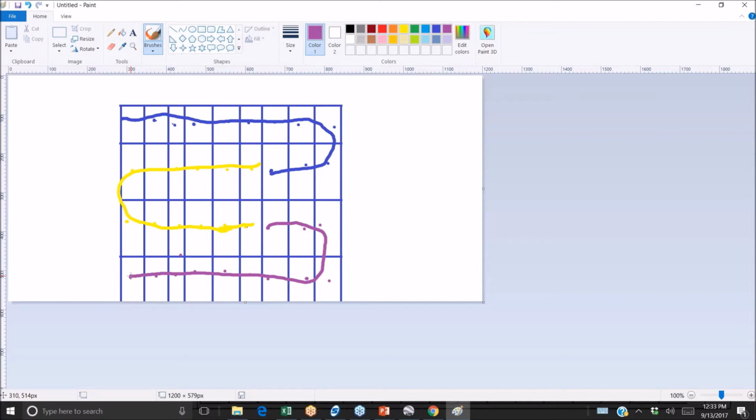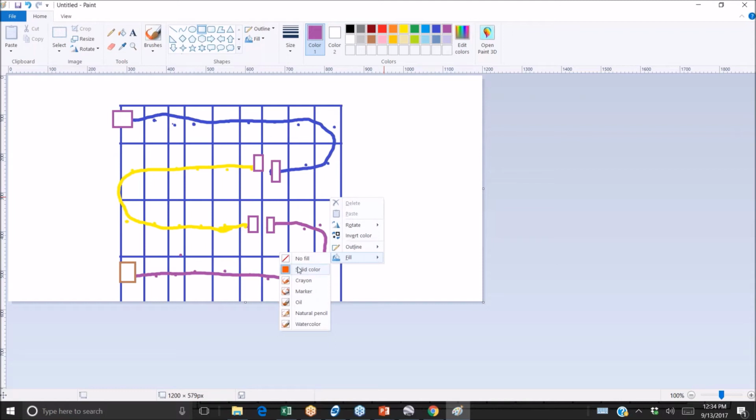Well, the problem is, especially with microinverter arrays, but even at a larger level, a very common failure point in the system are these custom-built connectors that go at the start and stop of every circuit. What we can see is that some of our connectors are located on the edge of the array, where they're accessible if there's a failure point. But the problem is these connectors here in the middle, if they fail, you're going to have to start taking the array apart in order to get access to those connectors.